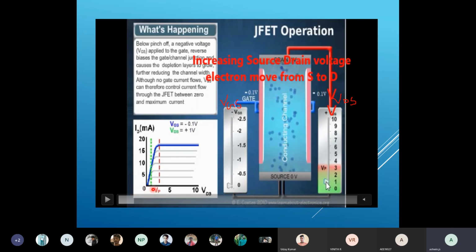And if you look at this graph, it is representing 0 to 1 that I am giving, and VGS equal to 0. I am keeping VGS equal to 0 at this level. If your VGS is greater, I get more current. If I increase it from 0 to 2, this graph will move from 0 to 2, and at that time you get the maximum current. This is the ohmic region, and the straight line represents the saturation region. Later we will discuss this in depth.